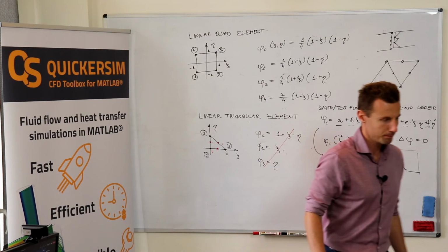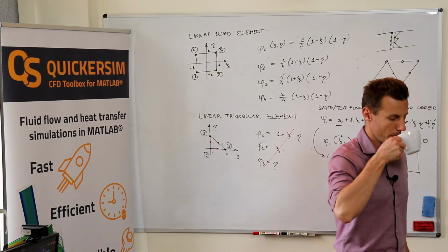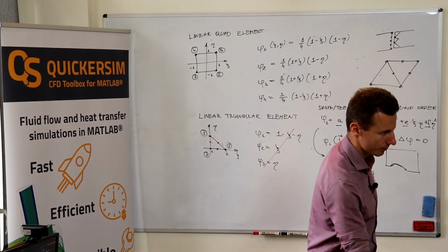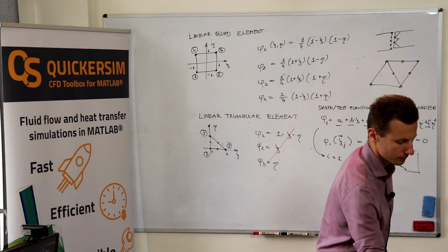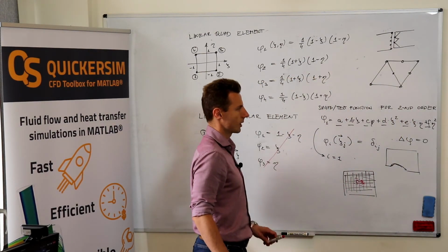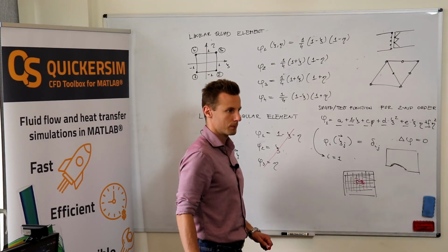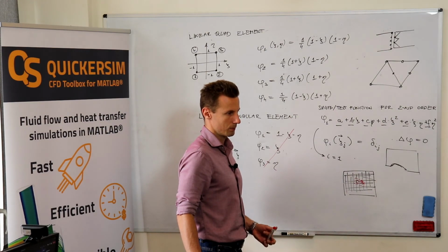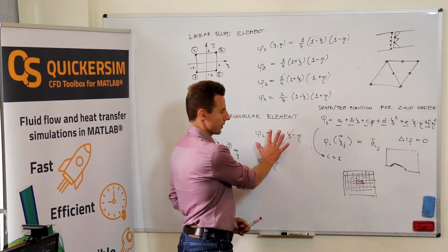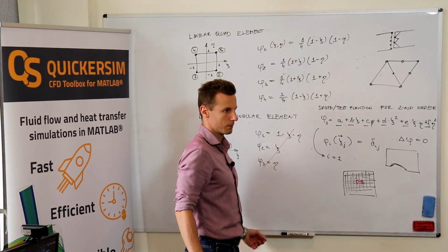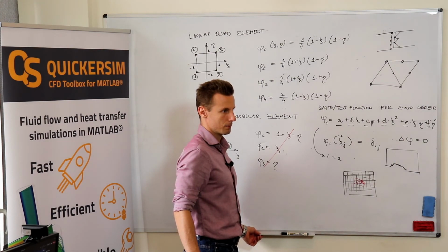I wanted to make sure that I understand correctly. When we have a second order element, the local functions stay the same even if it's second order geometry, and only the transformation becomes strange. Once again, when we have second order geometry elements, then the local shape functions are the same as we have just written, but... No, okay, we haven't written the second order, but yeah, they stay the same, and only the Jacobian changes when solving.